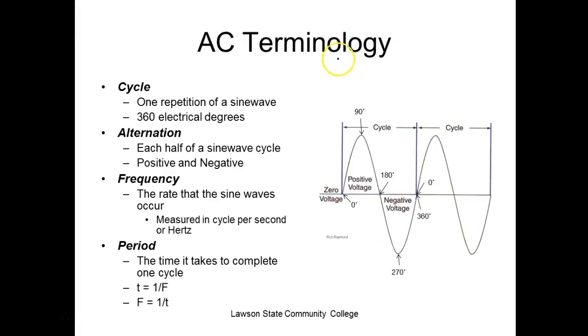Well, what we get when we transfer power is power is equal to V times I. When it's three-phase, power is equal to V times I times the square root of 3. So that means for less current, we can send more power if we send it three-phase. So this is why when we transmit power, they usually transmit three-phase instead of single-phase.